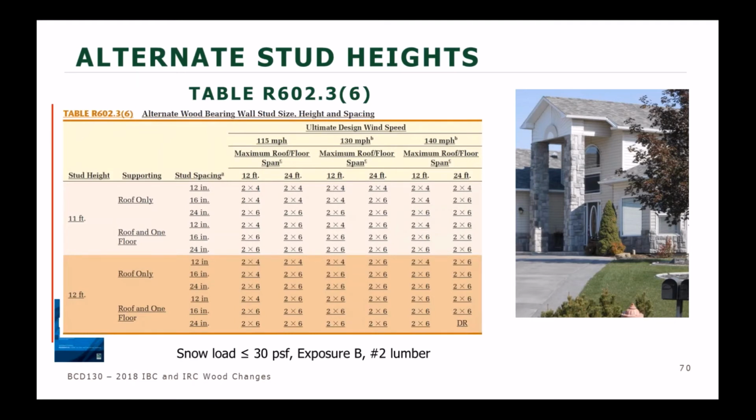And the intent here was to look at studs that were in lower wind regions, in higher wind regions, high and low snow loads, wind exposure categories, and try to put a box around, okay, when is it okay to use a 2x4 stud? When is it okay to use a 2x6 stud in these taller walls? And what goes outside the limits here?